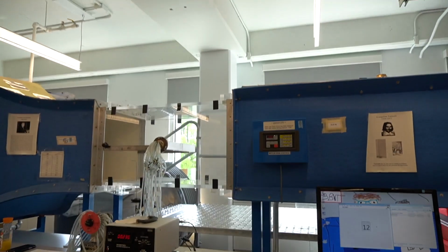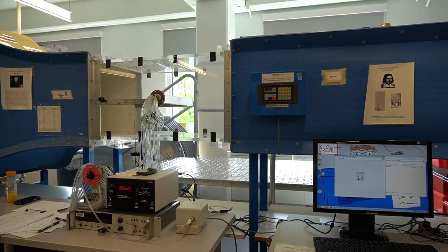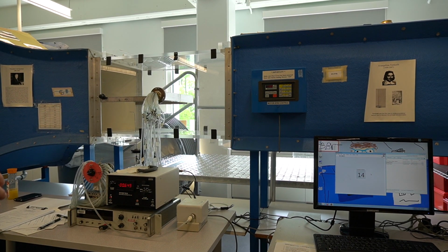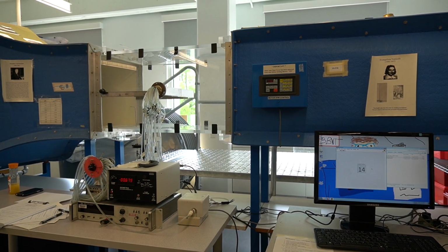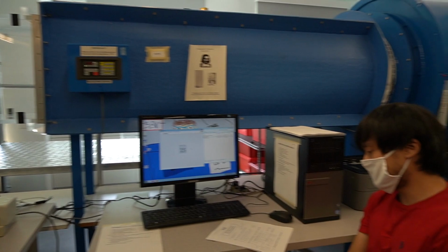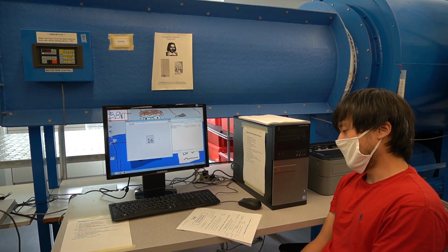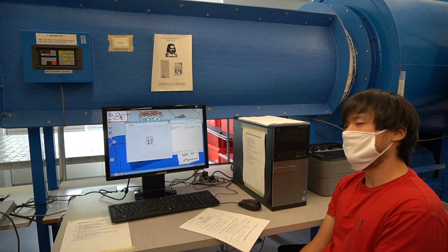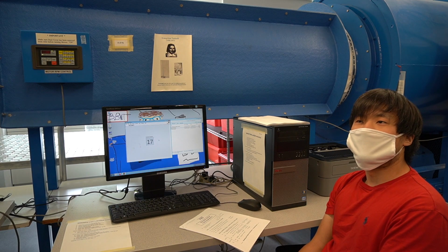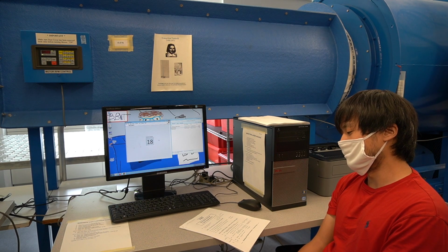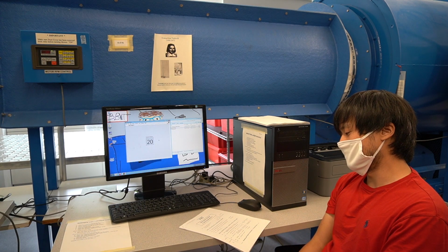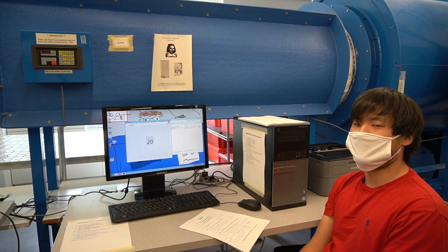Once we get through the 22nd pressure tap, what's left for us to do then? We'll be putting it through the system and trying another data point, right? Trying another change of variables. Yeah. So once we go through all 22 pressure taps for this G over H, we're going to change the G over H. If you're following along with your lab handout, this is for G over H of 0.5. We're going to be doing it for 1.5, 2.5, and 5.0, different gaps, for this plate height. Then we're going to exchange the 13% plate for the 37% plate, and run it at the same G over H's, except instead of 5.0, we're going to run it at 4.0 and 6.0.